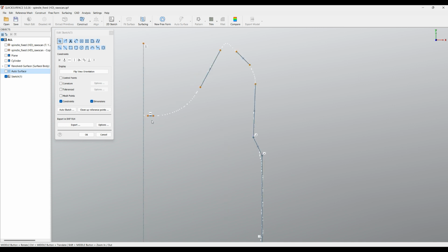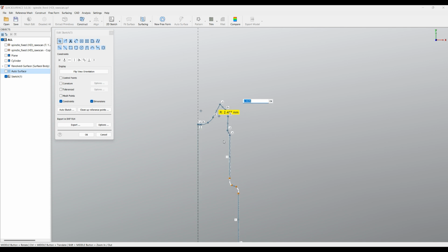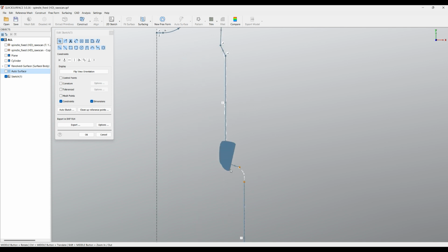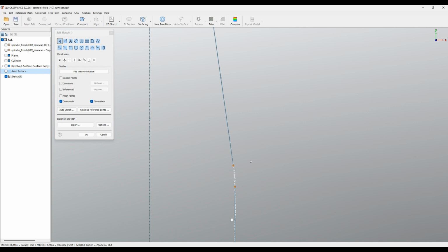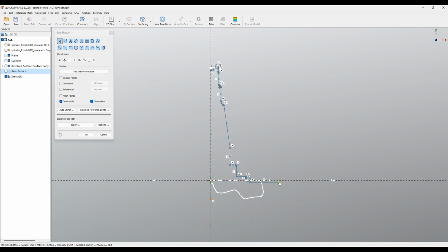Here you need to pay attention to this horizontal line, so it can create a nice and flat surface here. Continue intersecting with a single brush. Brush again to get a fillet. If you want more details about this process, you better refer to our tutorials, where we spend more time explaining every individual feature.